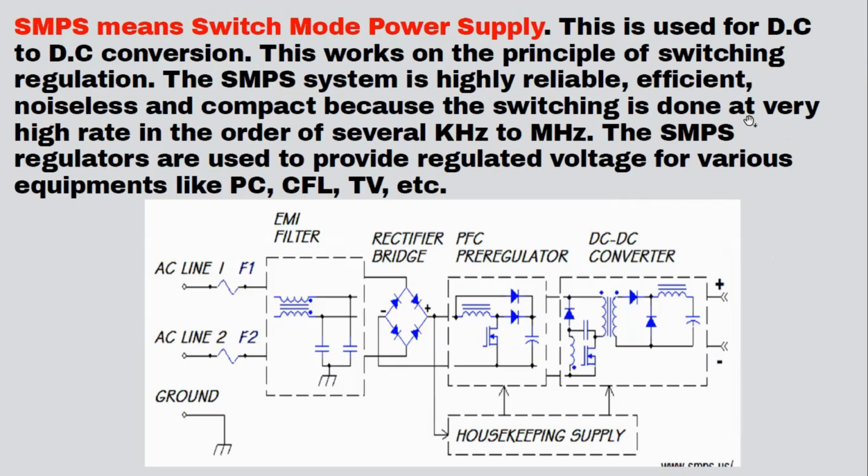You have to remember the switching is done. Since the name is switch mode power supply, switching has to be there, that is on and off switching, and it will be very, very fast, in kilohertz to megahertz. SMPS regulators are used to provide regulated voltage for various equipment like PCs, CFLs, TVs, and so on. I told you nowadays SMPS circuits are used everywhere.